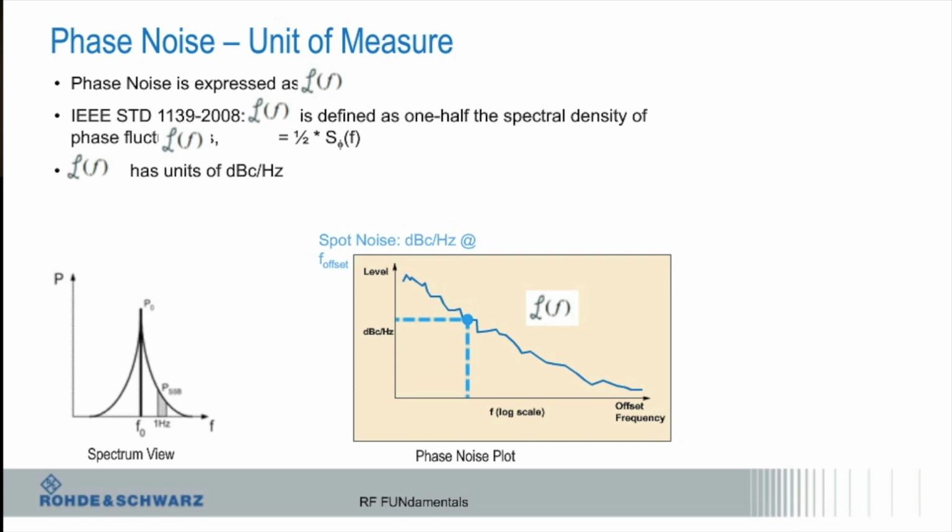And there are some other issues where you need a phase noise analyzer instead of a spectrum analyzer. But all said and done, can I resolve that signal within that bandwidth? At that level, it's not a problem at all. Any normal spectrum analyzer should be able to measure phase noise.